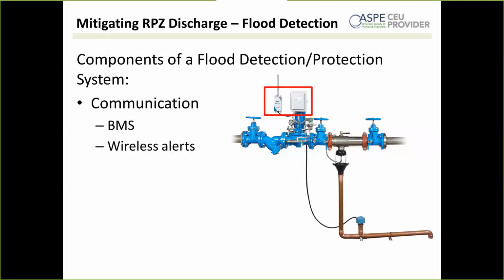With the sensors and interface, what suggested annual maintenance should be required for the items? Those sensors and interface, as far as I know, are reasonably robust. It wouldn't be a bad idea to go ahead and, during an appropriate time, trip that sensor. You can do it by hooking up a hose and pouring a bunch of water down that discharge line, at least for the kind that you see here up on the screen.